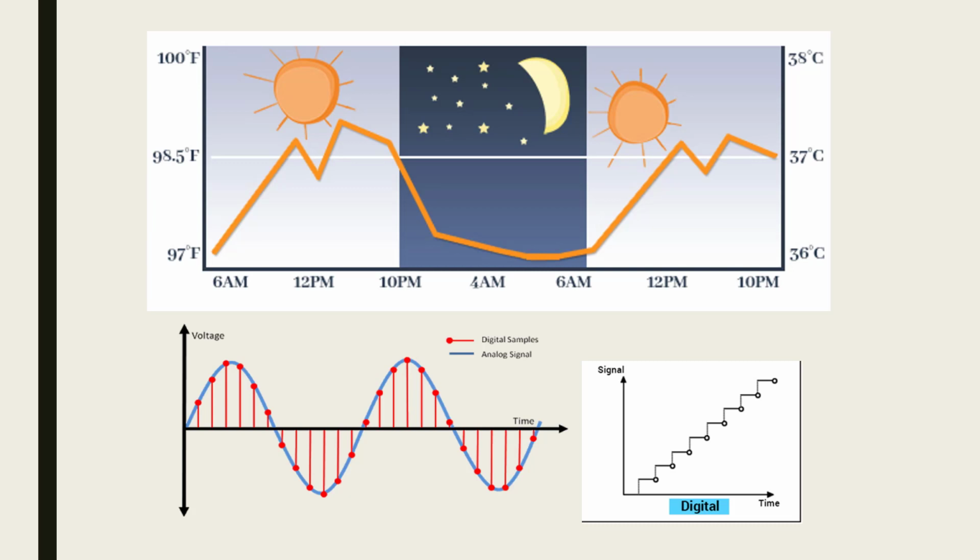So, one of the aspects of analog to digital conversion that's very important is the rate that you take those samples. And that rate that we take the samples is called, wait for it, the sample rate. So the higher the sample rate, the more frequently you're taking those recordings, those measurements, and by the way, that's measured in frequency. If we're doing 10 per second, then that's a sample rate of 10 hertz. So keep that in mind. Sample rates are measured in hertz.